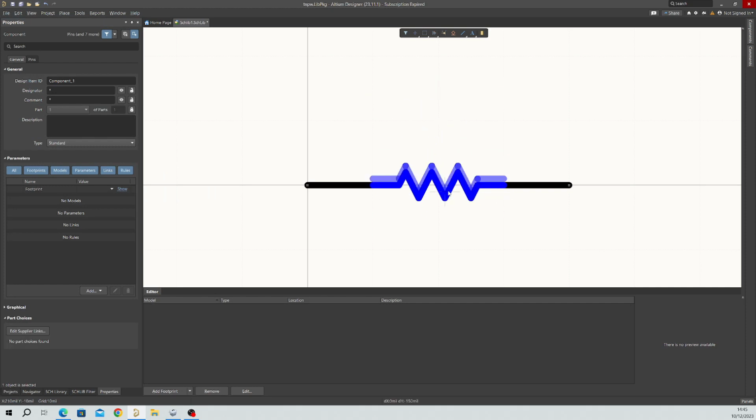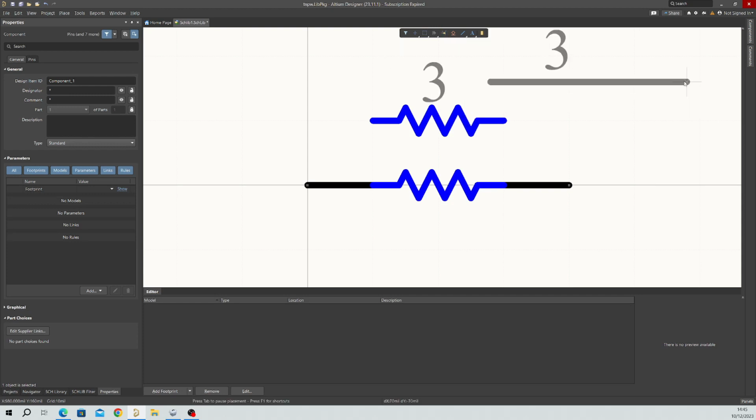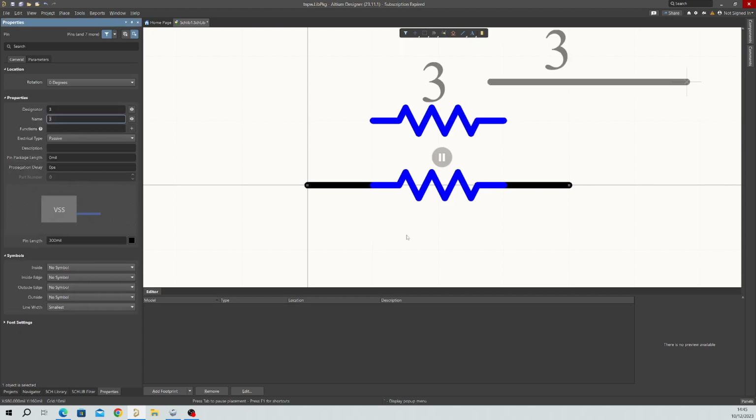As you can see, that pretty much overlays that. And then all we need to do is add some pins. These are quite cut down pins, so 100 length on that. They're passive. We don't really want to see them, to be fair, unless you do, and then of course you do. So just plot this up there.